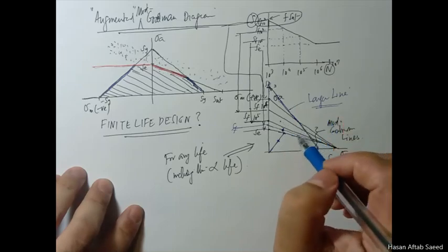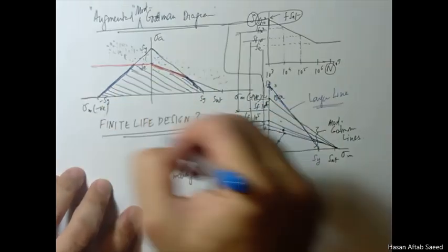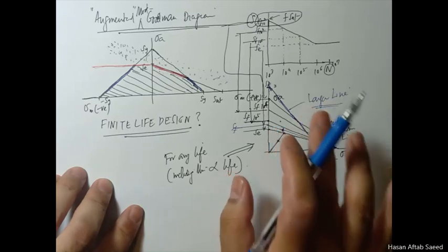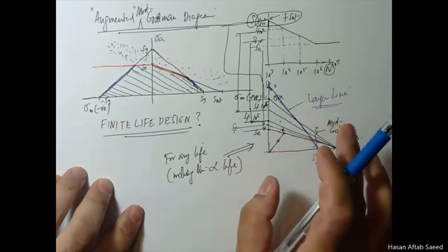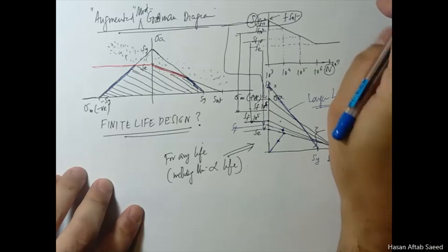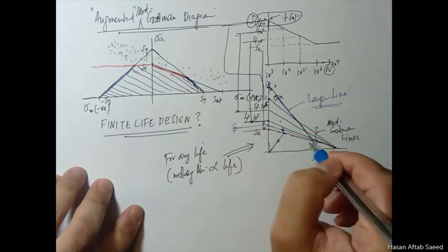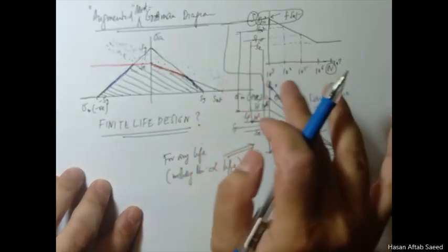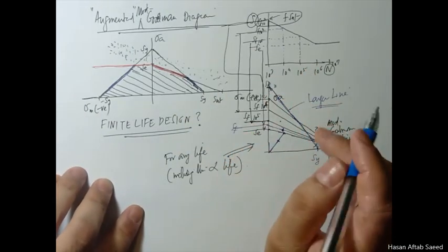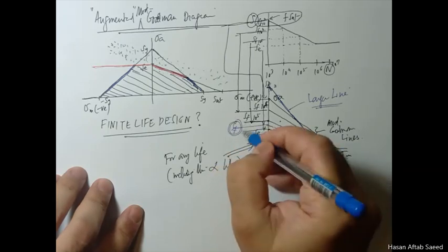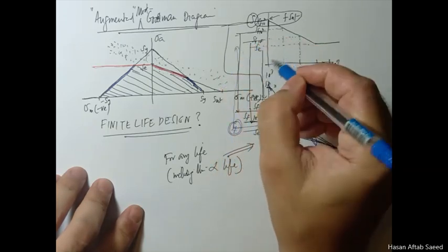Okay, and we don't draw these diagrams to scale and then measure. We'll use some equations, and you'll be introduced to those equations. Very easy to use. So here we are just talking about what the process is. This is very important to know, how you read these things, otherwise basically you'll be using equations. So you read this SF from here, and then you go back to your SN diagram.